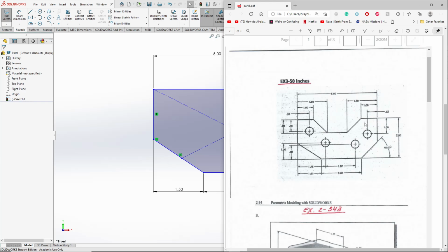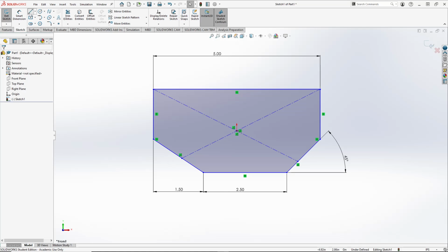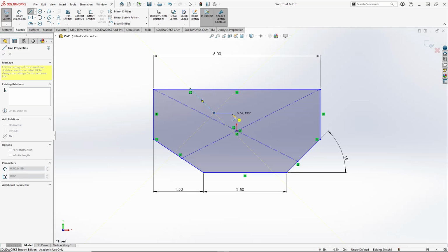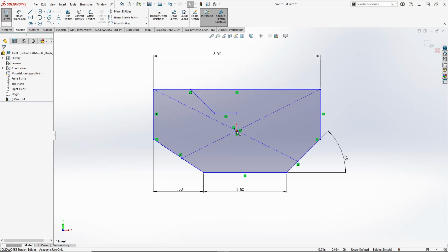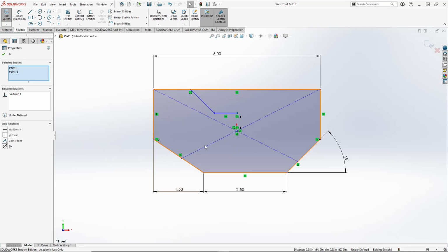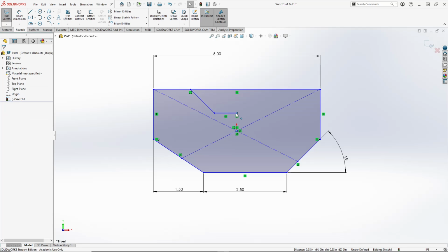So, looks identical on both sides, so we can mirror it. We only need to build one side. So let's focus on the one side we need. There's 1 inch in. That's where the cut starts. 1.8 inches in, it looks like, is where the cut ends. And then it just goes to the center line. So, down to the center line. I'm going to vertically align that with the center line so that whatever I change here, this will always stay. Could do it later, whenever, it doesn't matter.